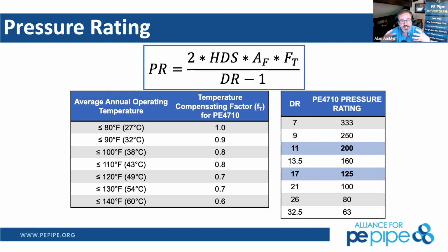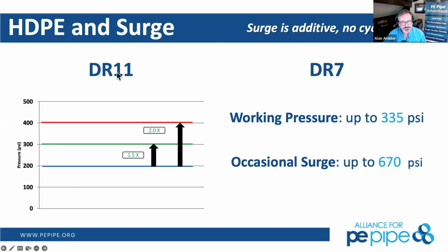So we understand with defined equations how we would derate the pipe in particular applications, because you might have an above ground pipe that's going to experience high temperatures. So here's just some common ratings for you. In reality, engineers don't always need that extra line of conservancy, but DR11 is what is mainly used for potable water. So go ahead and advance.